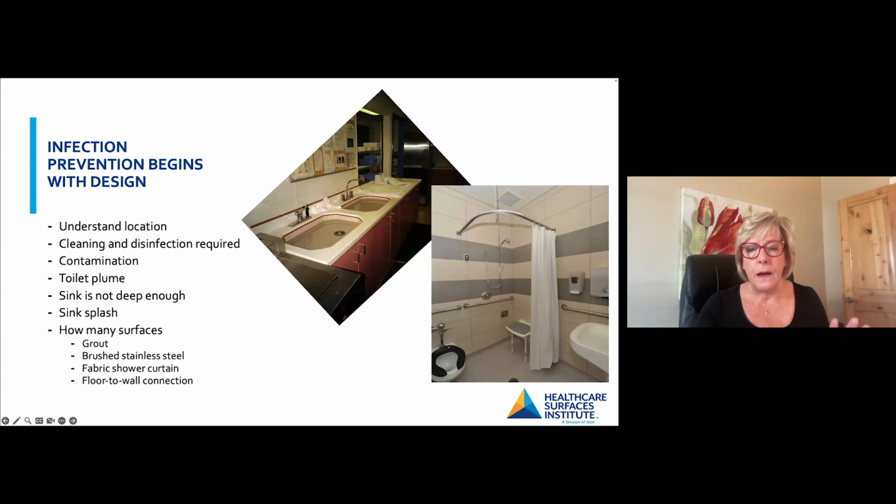I have been in destructive investigations where they actually peeled the tile off of the wall, and it was full of mold as a result of the leaking that took place as the grout broke down. So again, design considerations are really critical based on the location, how often these surfaces need to be cleaned and disinfected, and with what.